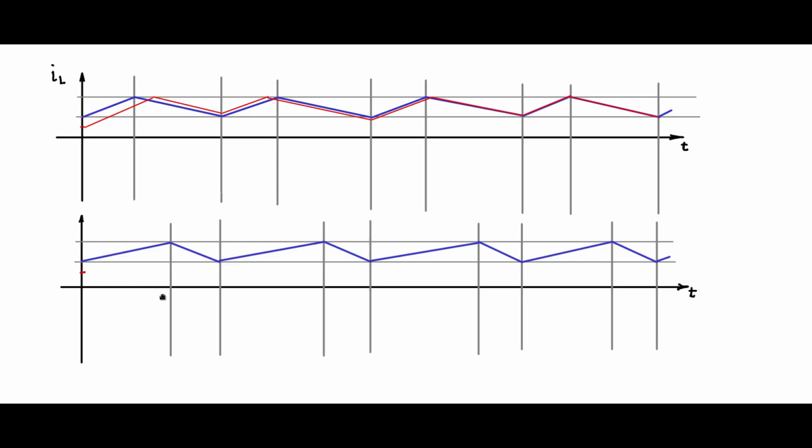So when you introduce a disturbance, now from this point onwards, it will start going parallel to this line. It will have the same inductor slope. So let us say it takes this line, it hits the top value here, that is the IL reference value, then goes down, resets again, because this is the time duration when the Q of the flip-flop is low.